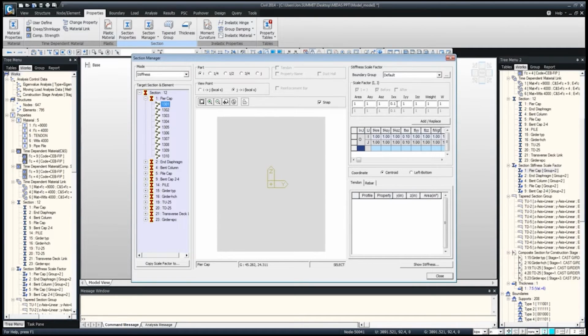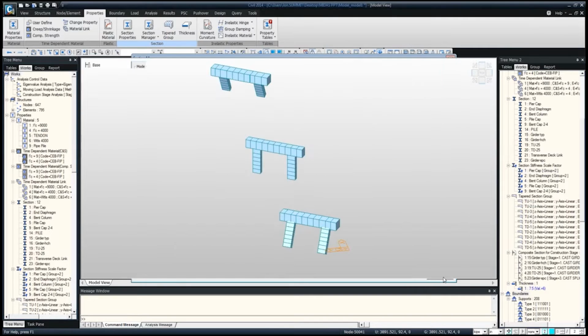And as I mentioned, we'll reduce that to 1/10 based on the compatibility torsion. So we can type a 0.1 in there, also select what stage I'd like to apply that with which boundary group, and add it. So that's how to input.